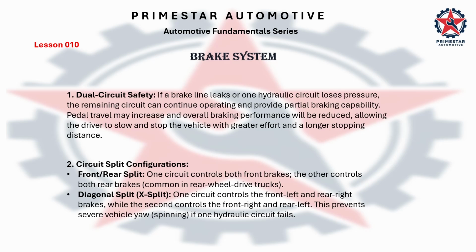Dual circuit safety. If a brake line leaks or one hydraulic circuit loses pressure, the remaining circuit can continue operating and provide partial braking capability. Pedal travel may increase and overall braking performance will be reduced, allowing the driver to slow and stop the vehicle with greater effort and a longer stopping distance.